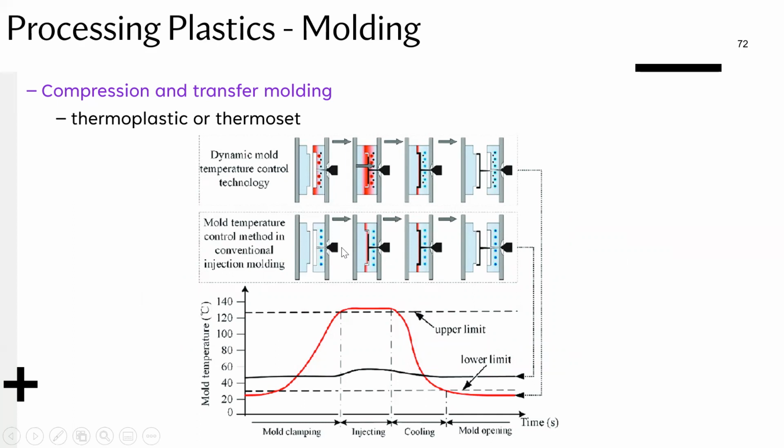The problem was that as you inject the molten polymer mixture into this cavity, because you've got sometimes really thin features, if this mold isn't at the proper temperature, it's going to cool down and solidify before it's reached all the points. So that's why you want to keep the mold at a heated temperature.